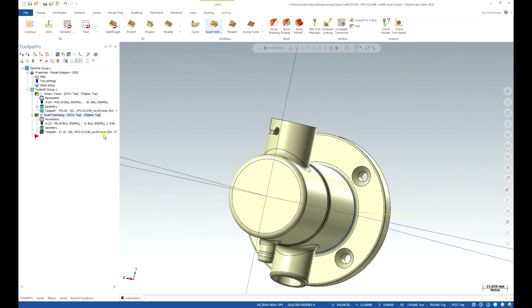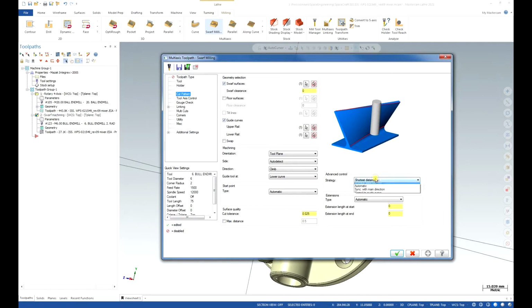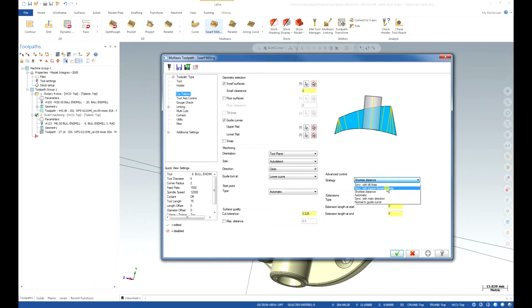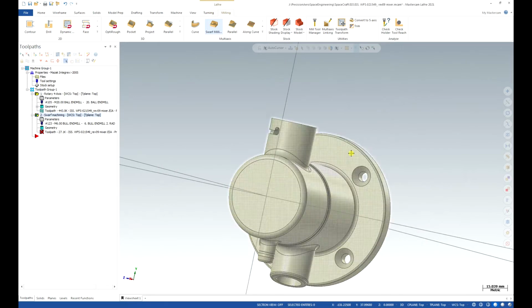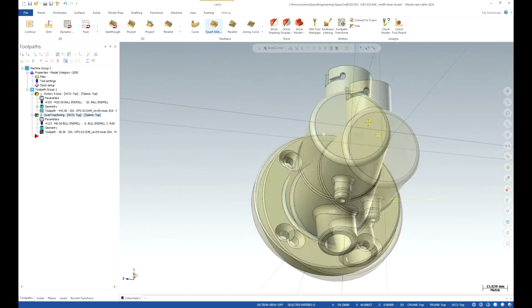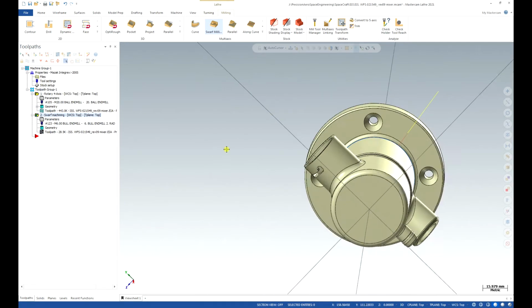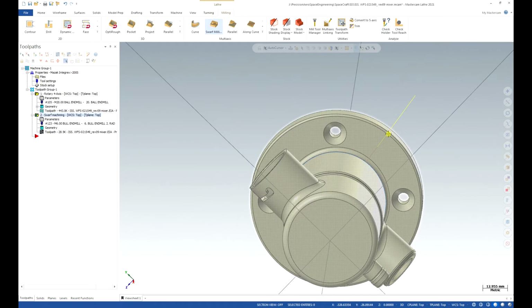So we have the result the same. If you synchronize between the upper and lower curve, and your face is changing the size, you can't get the proper toolpath. You can synchronize between upper and lower curve, but you need to remember to start both at the same point, going to the same direction and on the same height or on the same length.